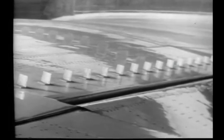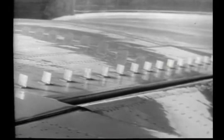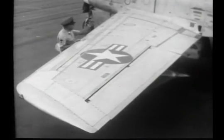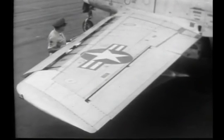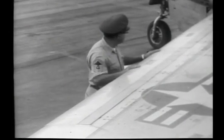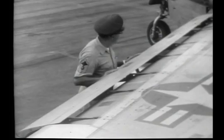Mixing of the outer flow with that next to the surface can be achieved through the use of turbulence or vortex generators. In many cases, such mixing is sufficient to suppress separation of the turbulent boundary layer if the adverse gradients to be overcome are not too severe. Blowing jets directed into critical areas are also useful. Frequently, these can be created by utilizing the pressure difference that exists on the aerodynamic bodies themselves.